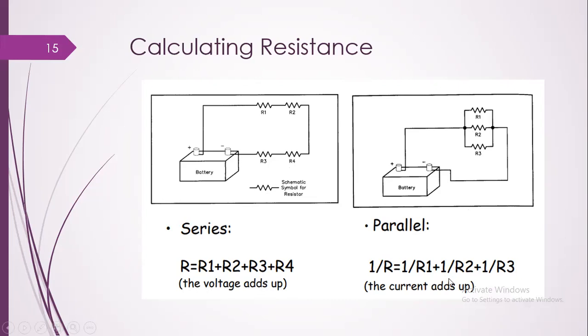The equivalent resistance formula is 1 upon R equivalent equals 1 upon R1 plus 1 upon R2 plus 1 upon R3. We also discussed that the current is divided in the parallel combination. So for calculating resistance, these are the two schemes, series and parallel, through which we understand the concepts of series and parallel connection of resistances, as well as their equivalent resistance calculations.